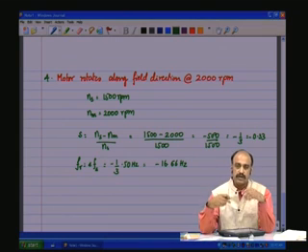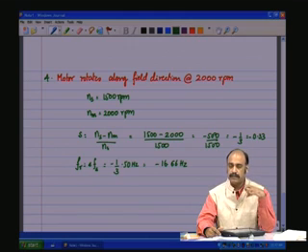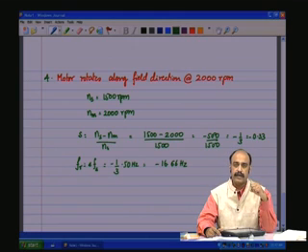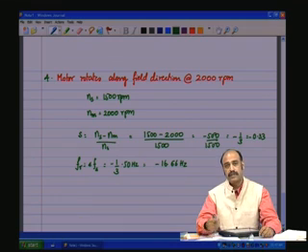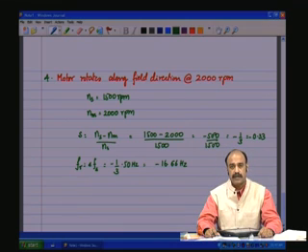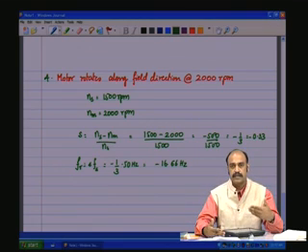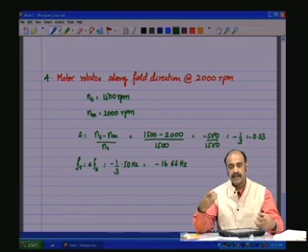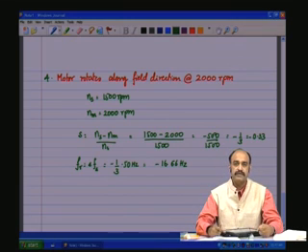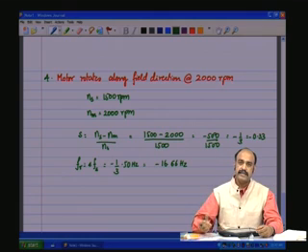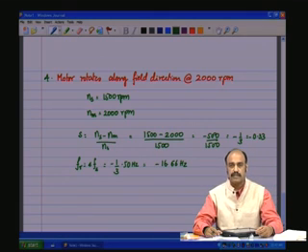So the motor is going to rotate not only by the electrical energy that is being supplied, but also aided by the gravity. And if the force due to the gravitational acceleration is high, then the shaft speed can go beyond the synchronous speed, in which case the mechanical inertial energy in the mass of the train is getting put back into the supply.